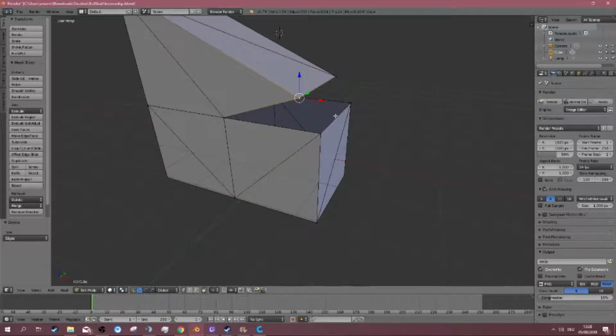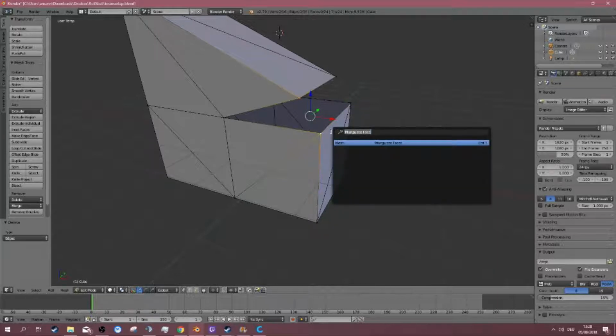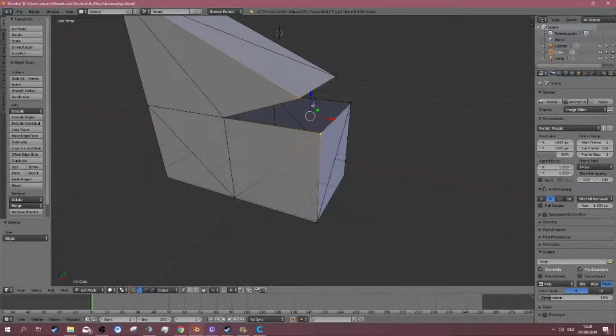You can merge vertices in Blender. You click one, then shift-click the second one, then press space and type merge. If you can't remember, there is a second way with a shortcut. That's click, shift-click, then Alt and M. And then it asks you where you want to merge.